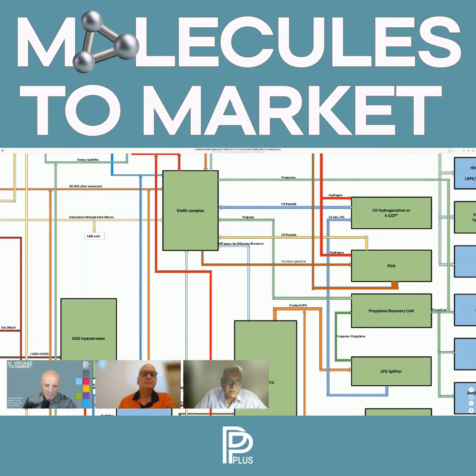Come to DHDT. Again, no problems. UOP, Axens, both of them have this technology. Topsoe also provides this technology. So if I have to do common licensor selection, Topsoe is the third agency which can provide that. There are others also, but the game is if I have to go for a managing licensor and make a choice between Axens and UOP, I don't have a problem because both have this technology. ABB and so many other people are there who have the technology. But if I'm looking at UOP and Axens who have a complete basket of processes, VGO hydrotreater, DHDT, again, no issue. Let's come back.